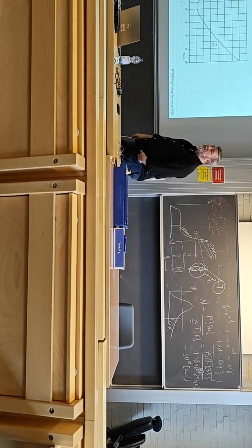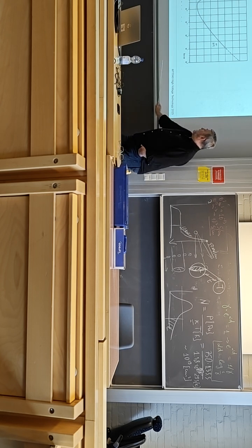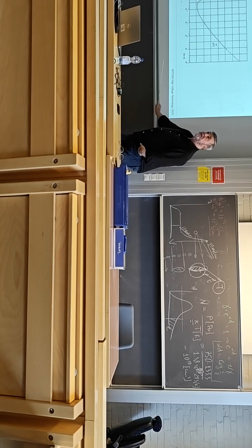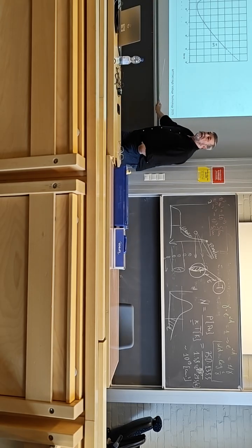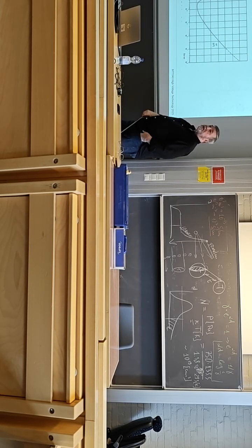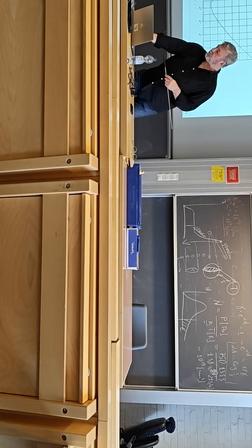In this way, you can estimate any combination. For example, you have a 10 centimeter gap, but the pressure will be, say, 100 millibars, okay? So 0.1 bar multiplied with 100, so you arrive at some pd, and then you take this value here, and then you just get the voltage there. So it's a combination of the distance and the pressure. Okay, that's how it can be used.